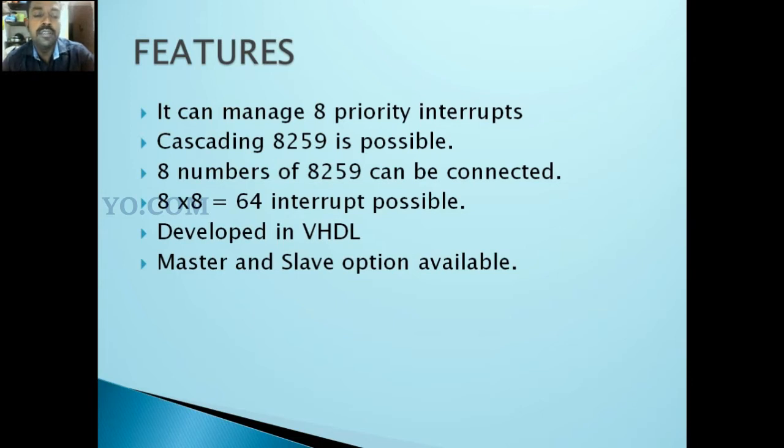Okay, right. So the PIC, after issuing an interrupt to the CPU, must somehow input information into the CPU that can point the program counter to the service routine associated with the requesting device. So how does the microprocessor find its interrupt service routine? The interrupt service routine is marked by a vector, that is an interrupt vector, which has an address. After the interrupt request, the service routine address is loaded onto the address bus. Based on that, the CPU executes the interrupt service routine present in memory.